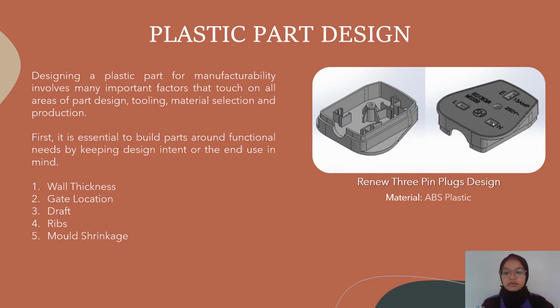Last but not least, mold shrinkage. The shrinkage that occurs during the plastic part molding process can be as much as 20% by volume. Crystalline and semi-crystalline materials are most prone to thermal shrinkage. Amorphous materials are known to shrink less.